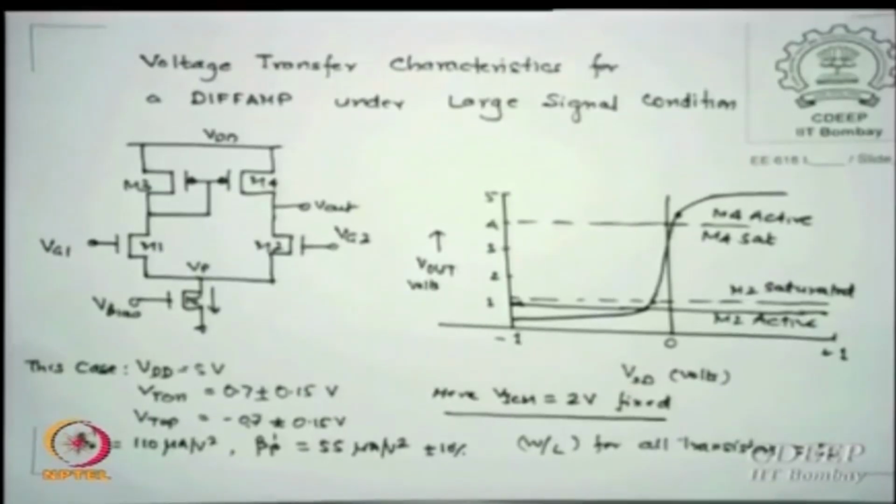But as far as we are right now concerned, the numbers are only numbers. We are not saying that this is specific to a technology. We may say okay, this is the data, or this is the spec. In reality SPICE will not allow you random numbers for a given node, they will specify each of them because their oxide thickness are known, their capacitance are known, they know everything there. So they will specify automatically these values which you do not have to even worry about, but if you want to read they will show you also what values they have been using.